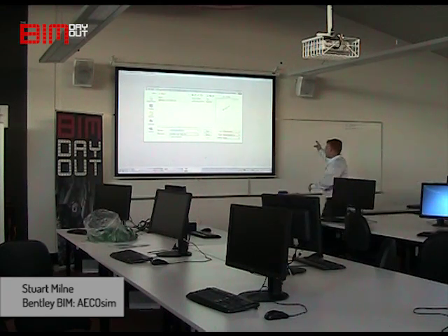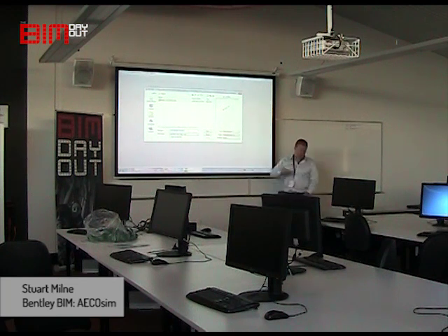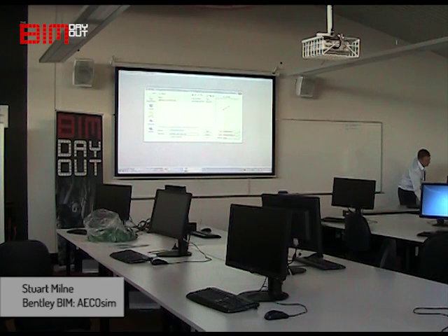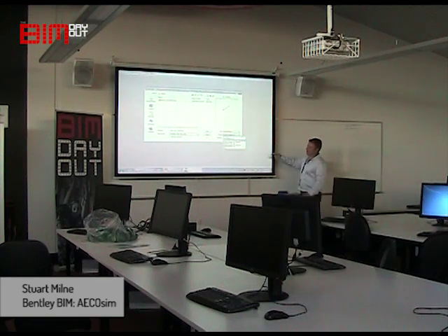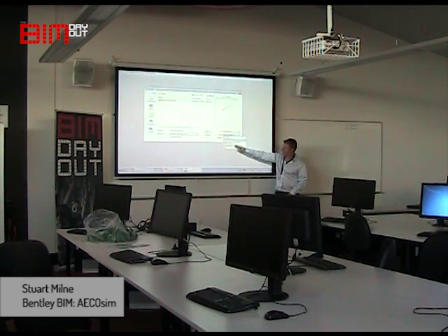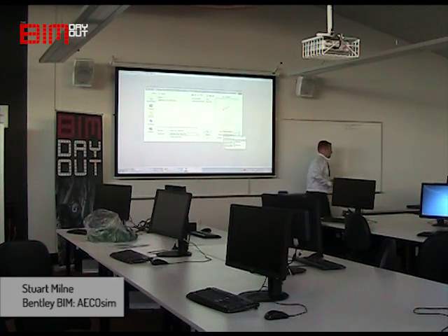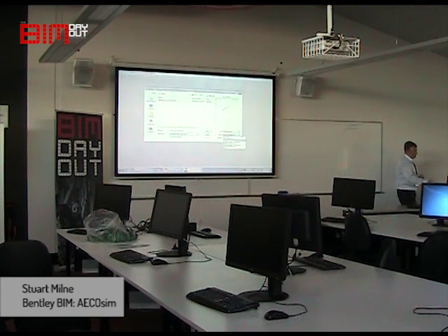Now, what you'll have under project here is a list of different projects. Typically, this is where people create their own custom projects, as they have different ones. But what we deliver at Bentley is different regional data sets. So you'll see here that we have a New Zealand, 2 different types of New Zealand ones, 2 different types of Australian ones, a US, which is Imperial, and for the moment that's all that's installed. What we want to do is take the building template AU for Australia,